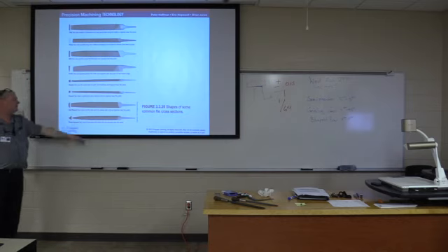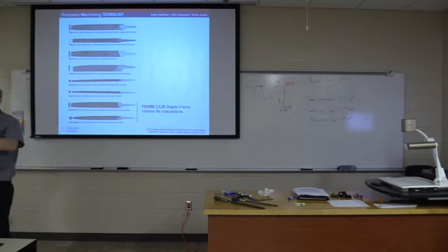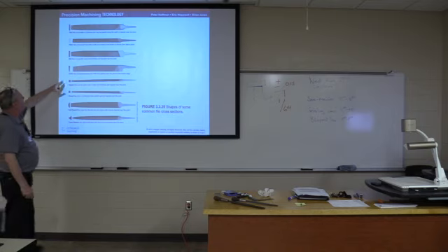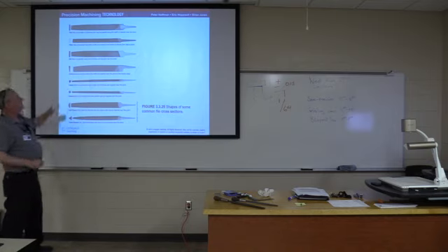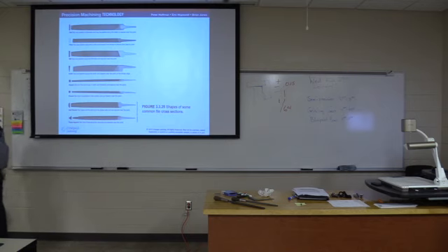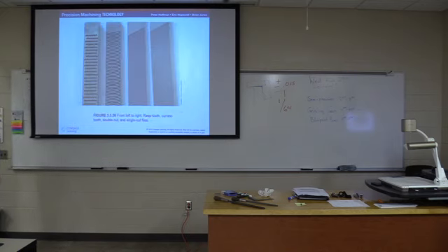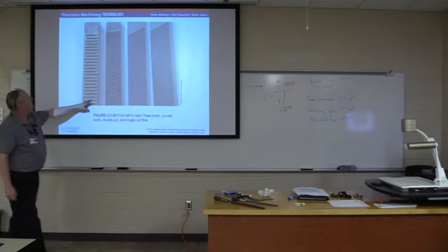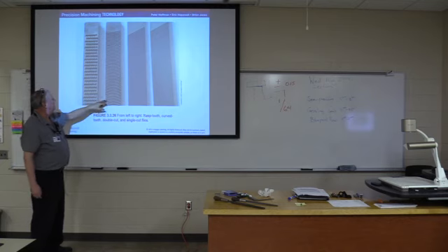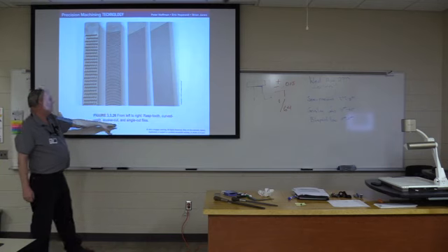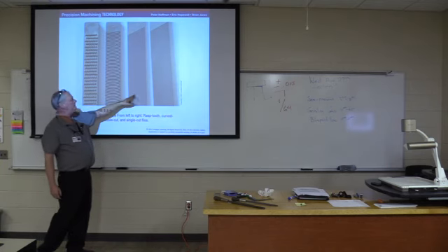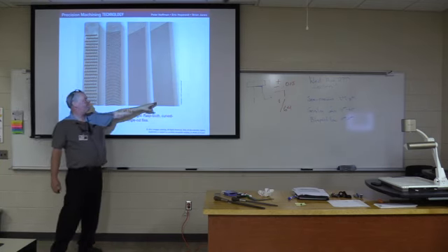They all have particular uses. So if you're working on rounded surfaces, use a triangular file. I like these knife files. They work really good, but there are a whole bunch of configurations. And here are the sort of more, you see these more in soft metals, but what we have here is something called a double cut and a single cut.